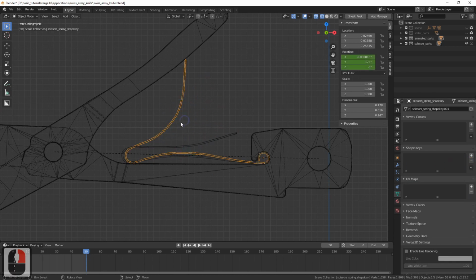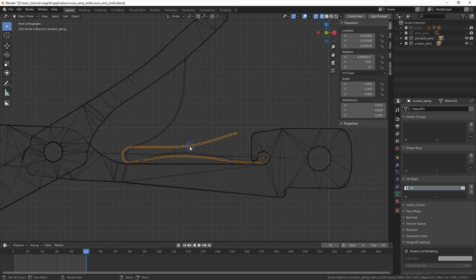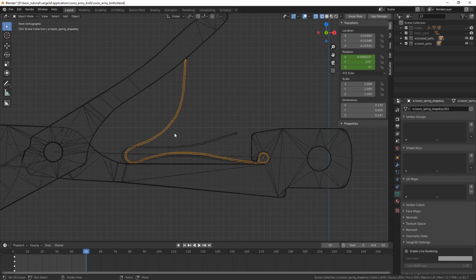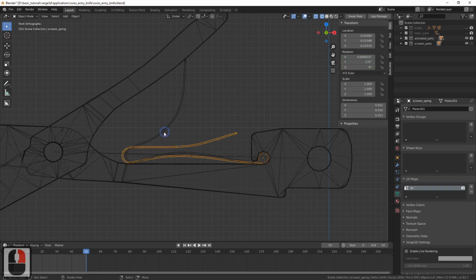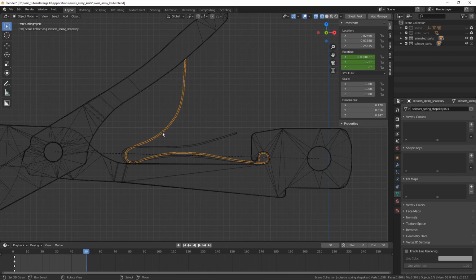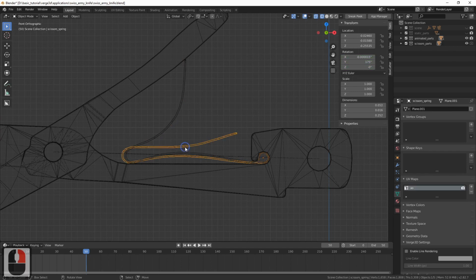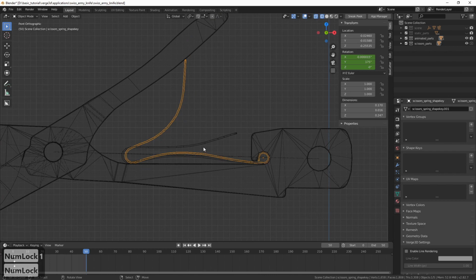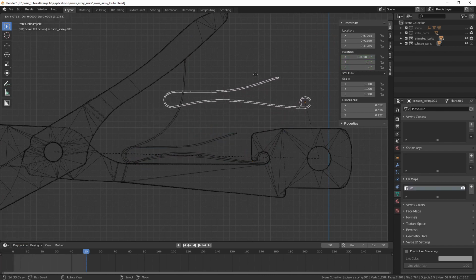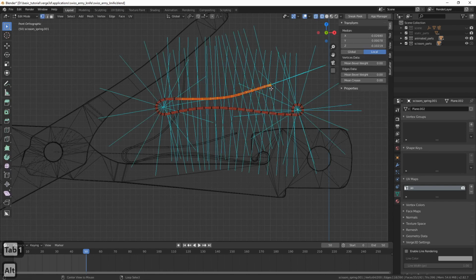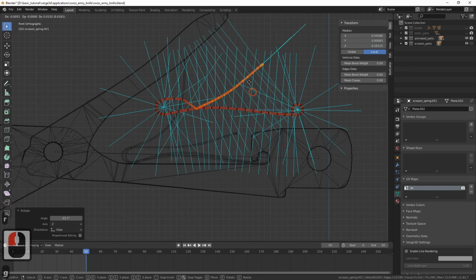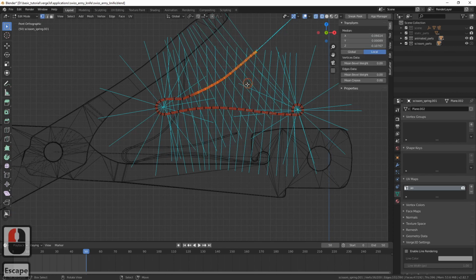We, however, already have a pre-modeled geometry for the shape key. It is important to have the topology of the second geometry exactly the same as in the original mesh, so that there is the same number of vertices and they are indexed in the same manner. But it is really easy to create because you can just copy the original mesh and only adjust vertices inside, making sure that you are not adding or removing vertices or applying any modifiers.